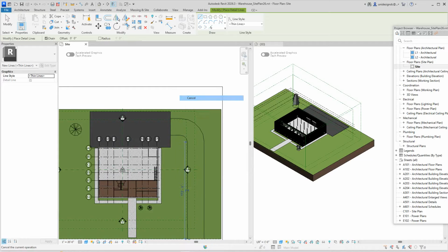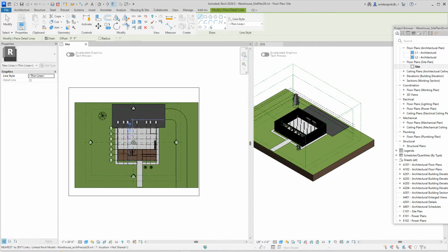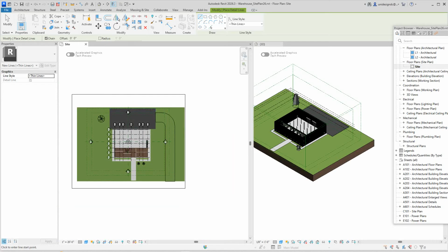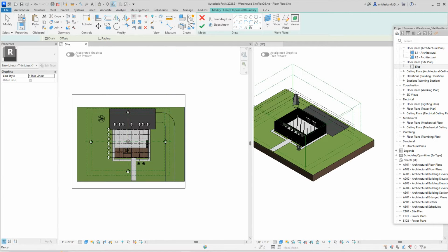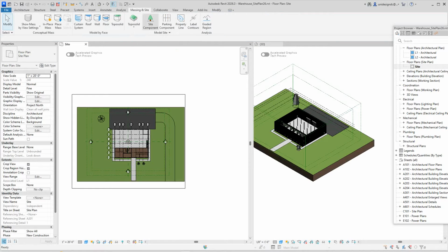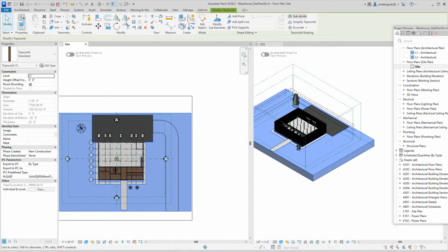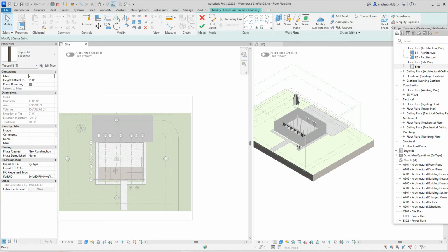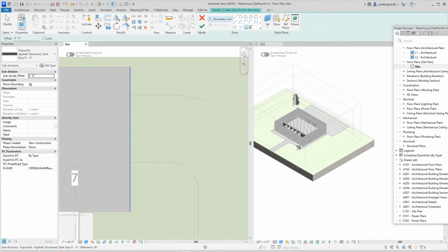Now we've got our lines in and everything, that's good. But that has to be under Site and Massing, again, Topo Solid. I'm sorry, cancel that out. We'll select the solid here, the site, the topo, and then we'll do a subdivide. So we'll just pick lines on these lines here that we created.